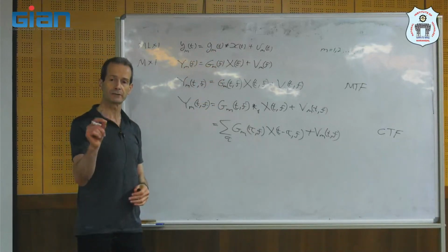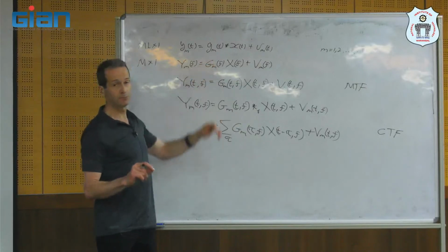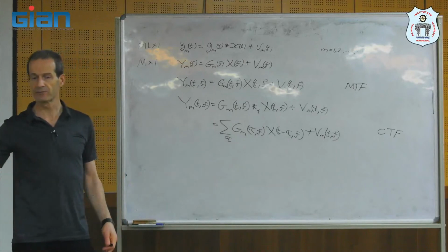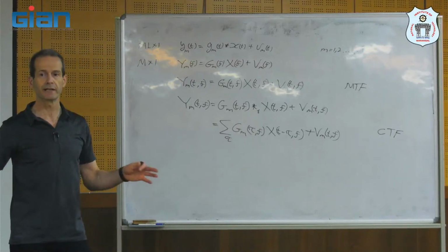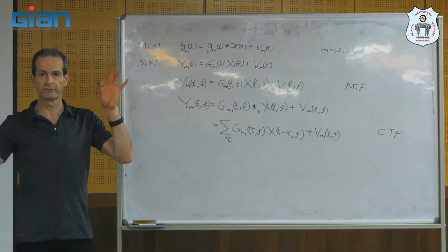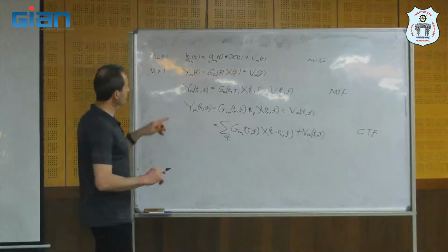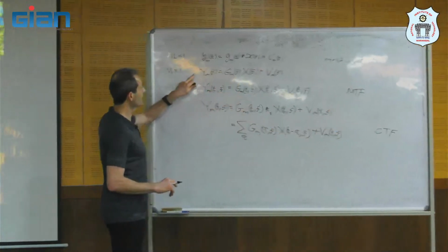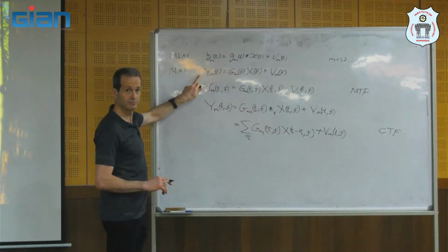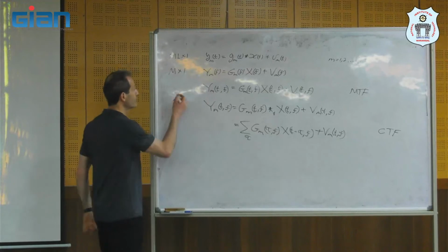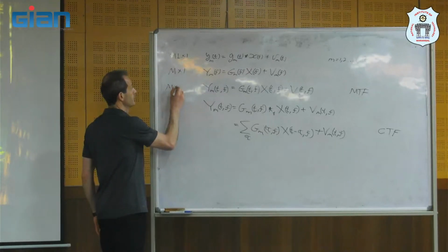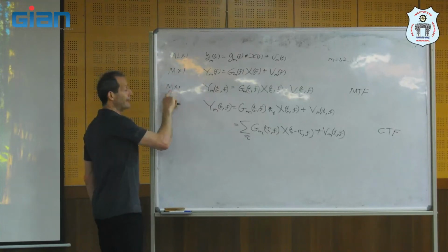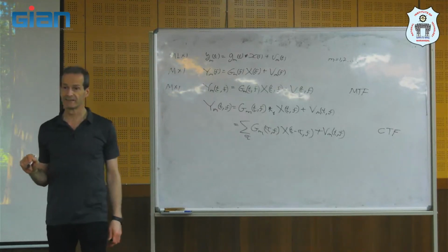So when we have short impulse responses, so we have just a few reflections. We don't have many reflections and reverberation. So under the MTF approximation, we can also work similarly to the Fourier transform. So we can work with filters of length M for each frequency.